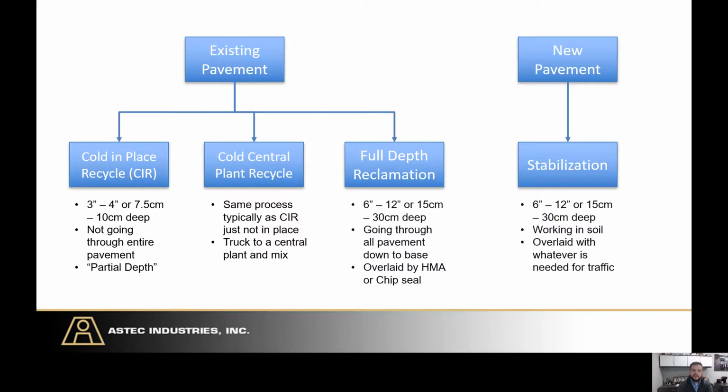Cold in-place recycle is usually going to be 3 to 4 inches deep. We're not going through the entire pavement structure, so we're not going all the way through the asphalt structure. Sometimes that's referred to as partial depth recycle. Our intention there, and we'll get into some more details, is to really break up the crack structure.